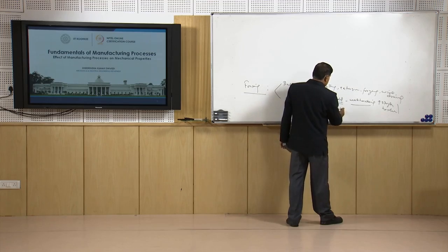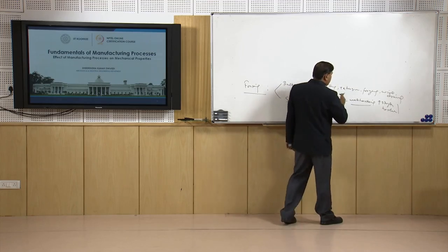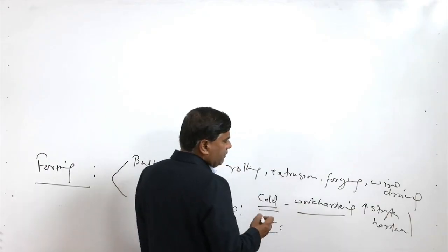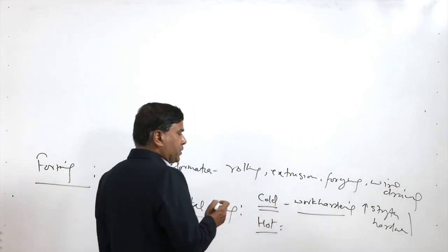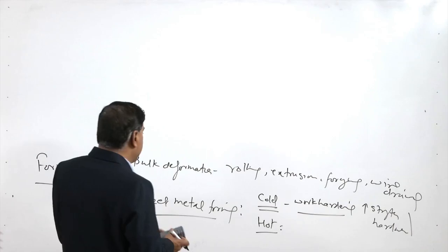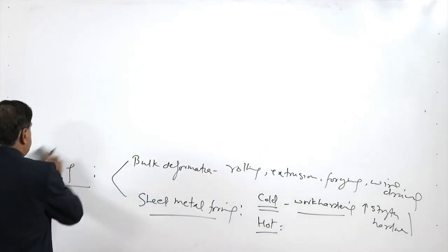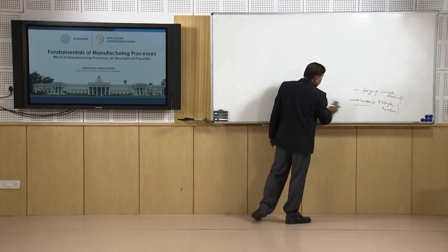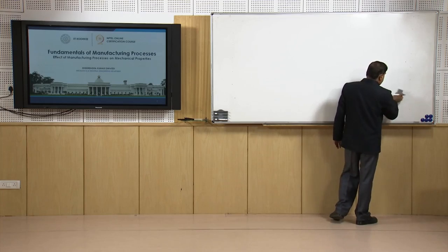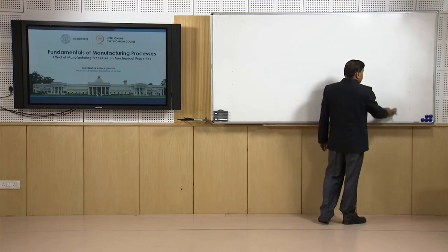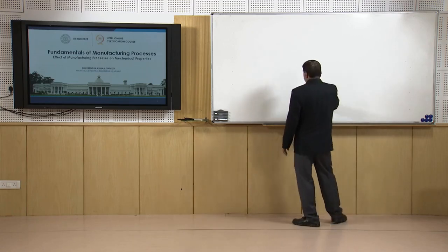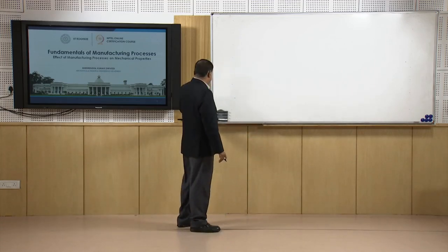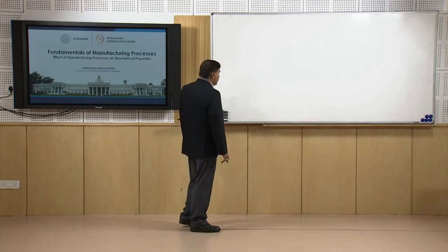On the other hand, in hot processes like hot forging or hot extrusion, the extent of work hardening is limited, but the microstructure is well controlled for grain refinement, so that the desired combination of mechanical properties can be achieved. And that is why, for realizing a very high strength to weight ratio in products made by forming based processes, most of the automotive components are subjected to bulk deformation based processes, so that the strength and strength to weight ratio of the product can be improved.